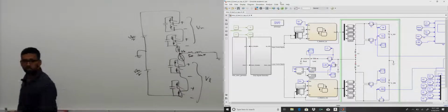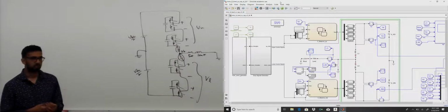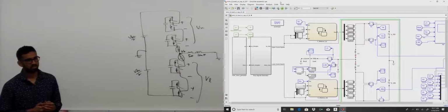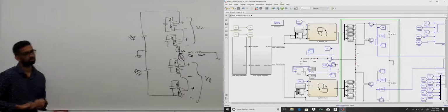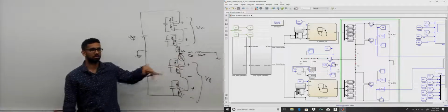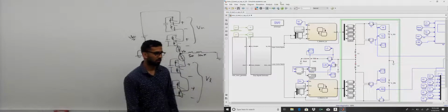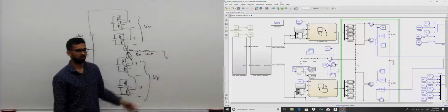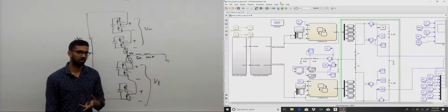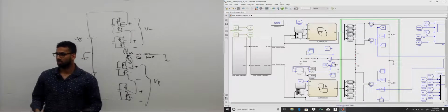Sorry, one question. If the load is specified completely in terms of R and L, how can you specify P and Q together? Because you control the voltage, right? You can only control the voltage. If you control the magnitude of the voltage, then P and Q are determined by L and R, right? You can control the magnitude and phase angle. Phase angle with respect to what? With respect to ground, or with respect to the impedance angle of the load? Phase angle with respect to 0.